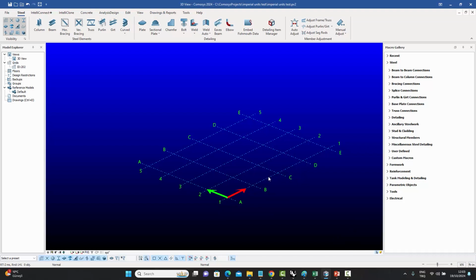Now, in principle, this feet inch format, because it's a fractional format, is limited in its accuracy to 1 over 32 of an inch, which is less than a millimeter, so it should be fine. But let's say you wanted a much more exact grid distance, an exactness which is more than 1 over 32 of an inch.